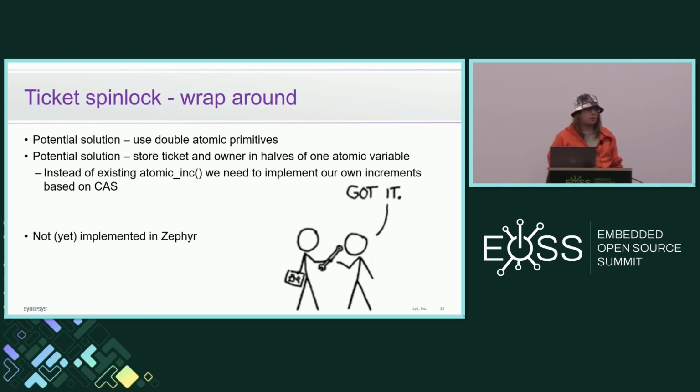That's a good question, and to answer that, I need to check how the hardware Spinlocks are implemented, but generally, even the original Spinlock implementation required these atomic read-modify-write variables. So I'm not sure if and how this original Spinlock was implemented for them, but if they use some other things instead of this read-modify-write atomic instruction, probably there could be a way to implement it, but I need to check this hardware specifically first. It really has a lot of influence on how we can or cannot implement it.